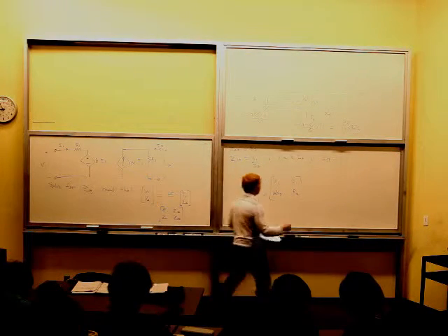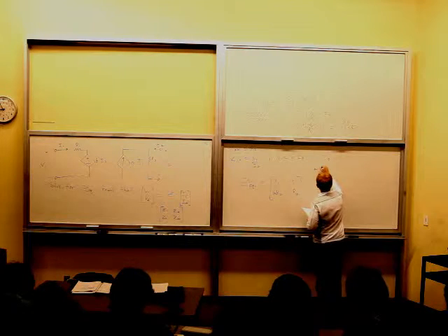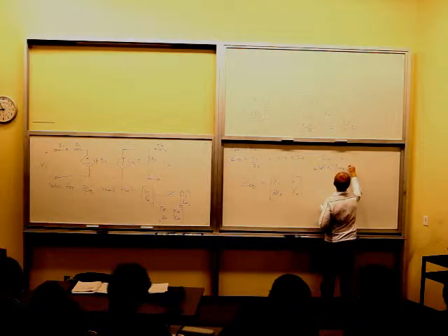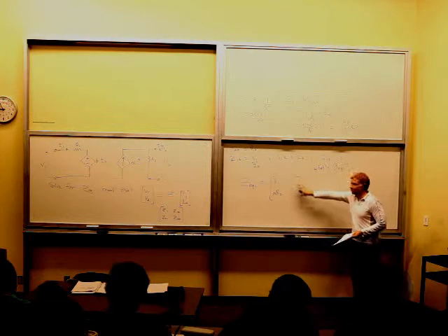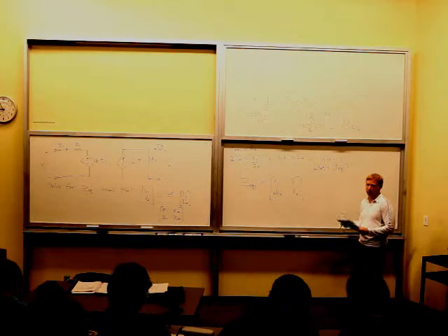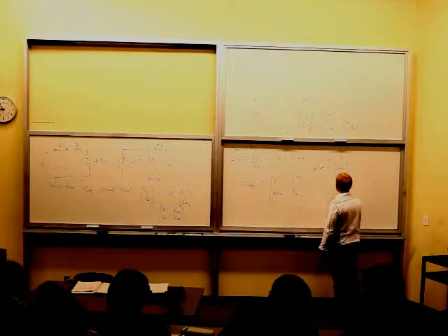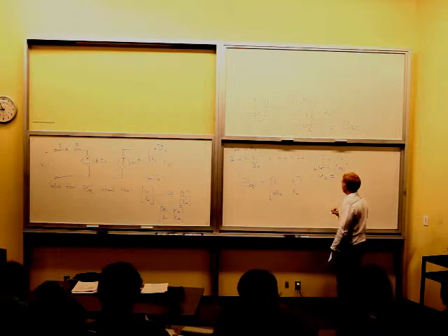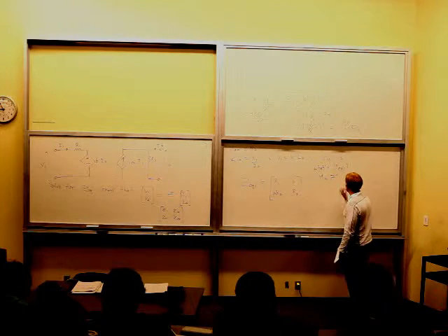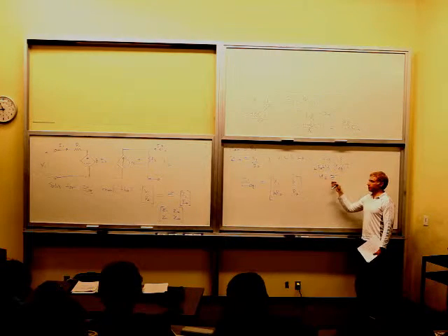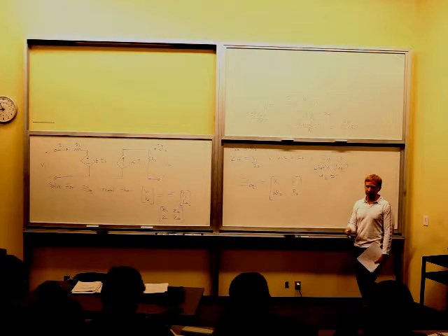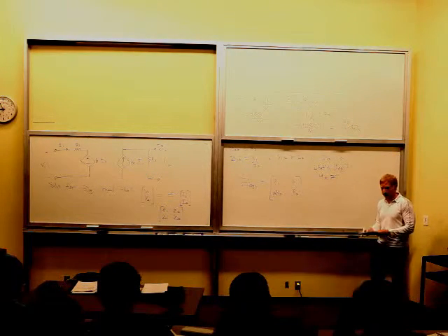So part B said, what's Y equivalent 1? Given this Z matrix, what's an equivalent Y matrix? That being, Y is equal to the matrix inverse of Z. So remember that these guys are inverses of one another. If I had Y, I would take the inverse to get Z. If I have Z, I would take the inverse to get Y.